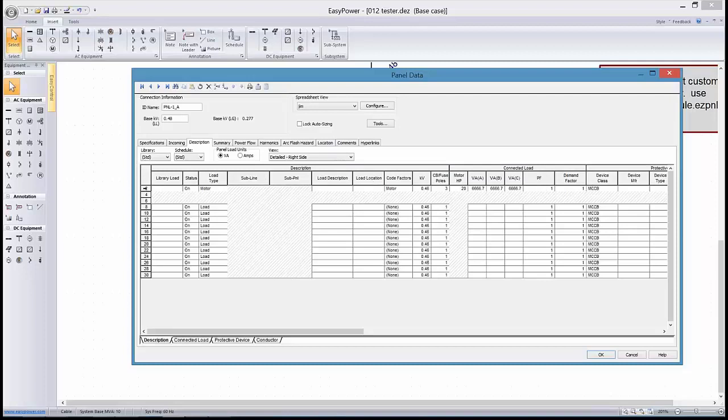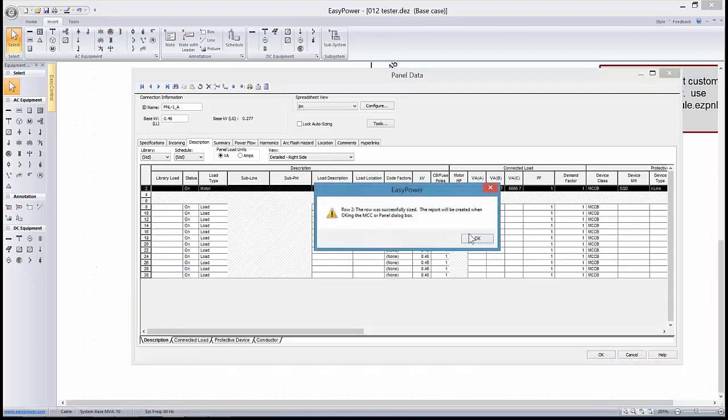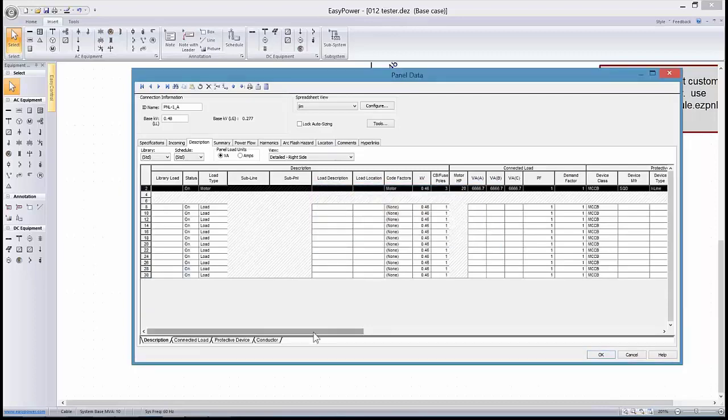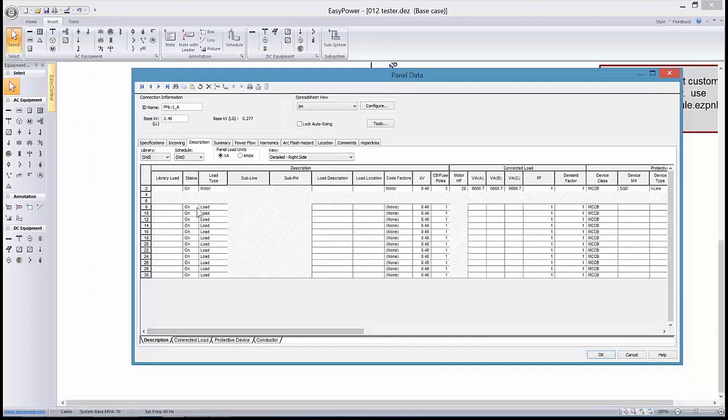I will go ahead and use auto design to size the protective device and the cable conductor. So you can see that we've got a Square D part number. And let's go ahead and set up a three-phase linear load. Let's say these are heaters in a remote building. So let's say we've got 2200 VA per phase in each of the three phases.